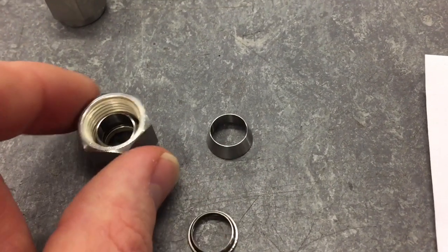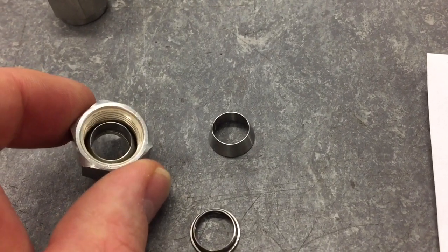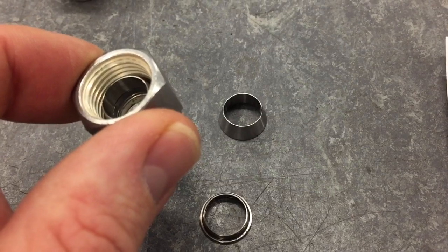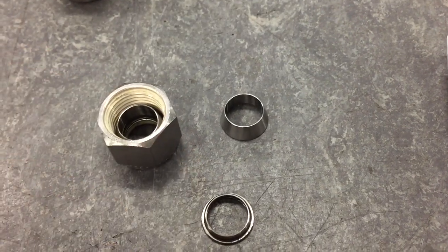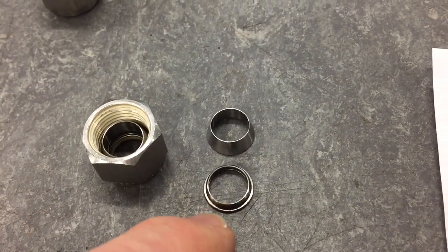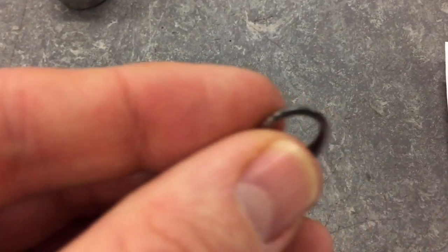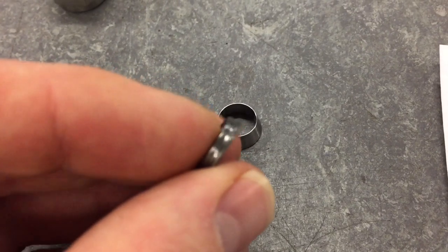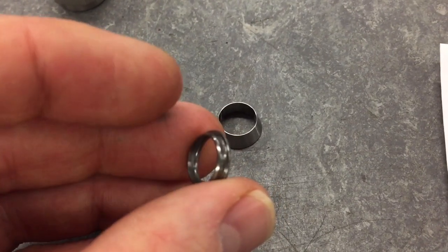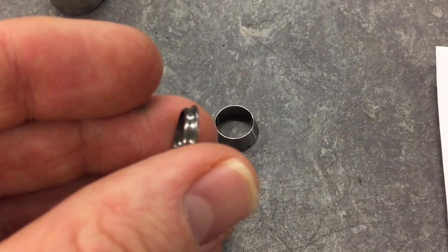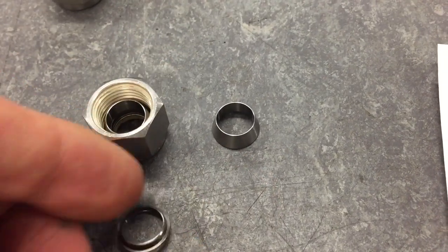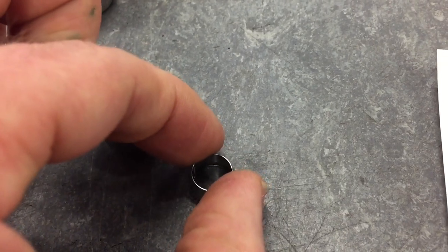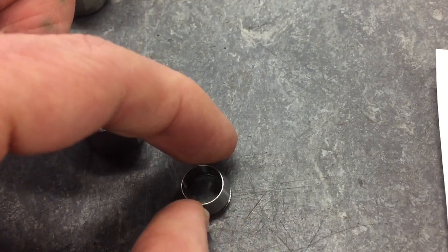It's placed in the nut first. You can kind of maybe see a little bit of it down there, but the larger piece is sitting on top. So this needs to be placed. If I just bring this in closer, we want to make sure that the larger part of the ferrule, or the lip there, the back part here, is down like this, and then the larger part kind of sits on top, just like that.